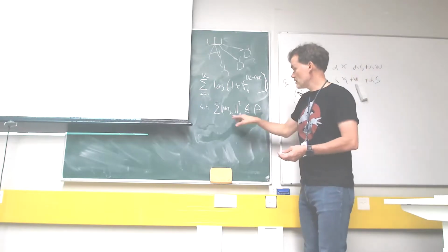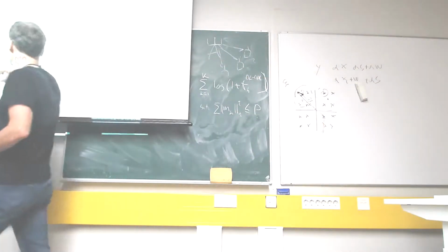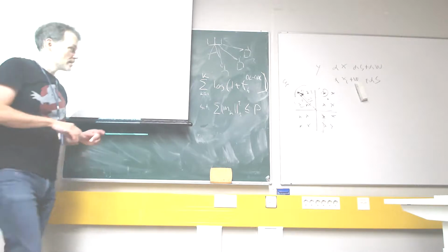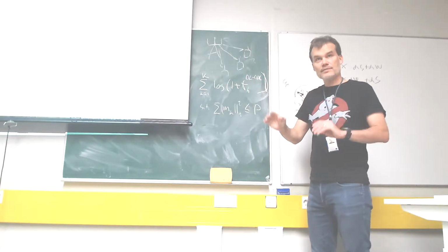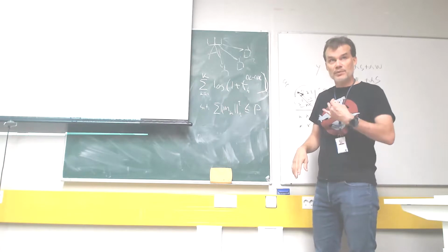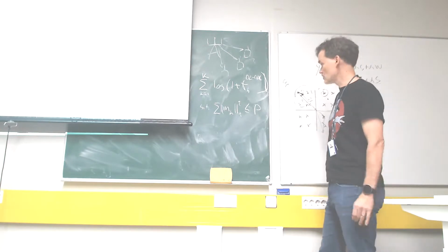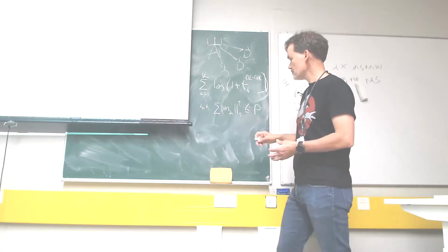Now the SINR would be h_k Hermitian times m_k, and p_k would be included in the u_k. It's equivalent. Now, if you want to plug these SINR expressions in here, there is no way you can solve it optimally. You can start doing all kinds of relaxations to get a local solution, but optimality is not guaranteed. So the steps to solve this: the first step,